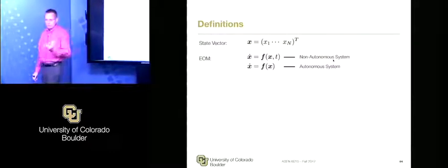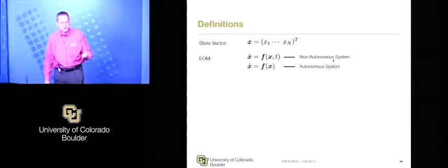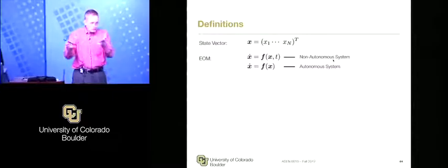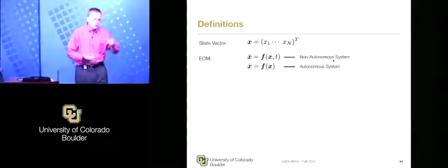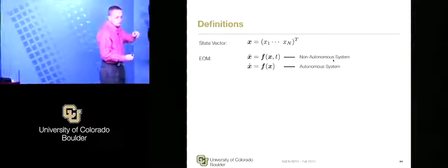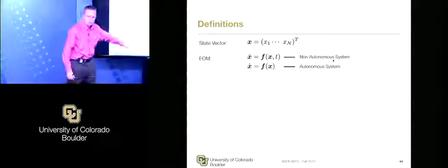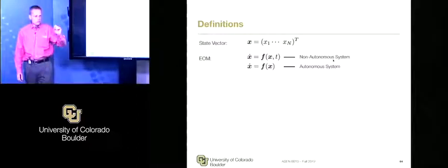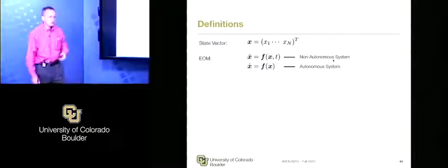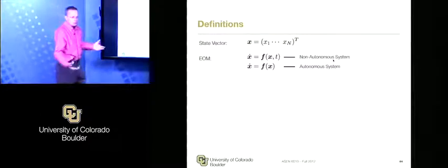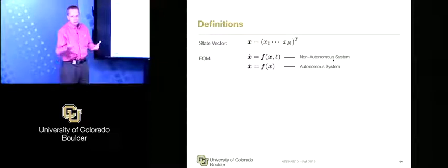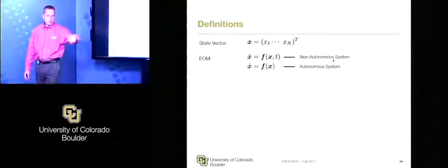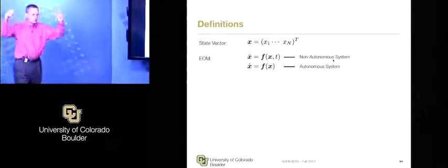But in real life, what happens with the quaternions when you integrate them numerically? Are they going to continue to have unit length? They're going to slowly deviate, depending on the quality of integration technique that you're using. So you might have to worry about enforcing constraints. You can have redundant formulations here, and the equations of motion work just fine. I can deal with a 7-dimensional or 15-dimensional representation of it. Just the equations, of course, have to satisfy all the inherent constraints. I don't have a 7-dimensional problem. It's really just 4. I've chosen to use 4 because there's some benefits. But then in the integration, after every step you might renormalize your quaternions to make sure they don't grow unbounded.